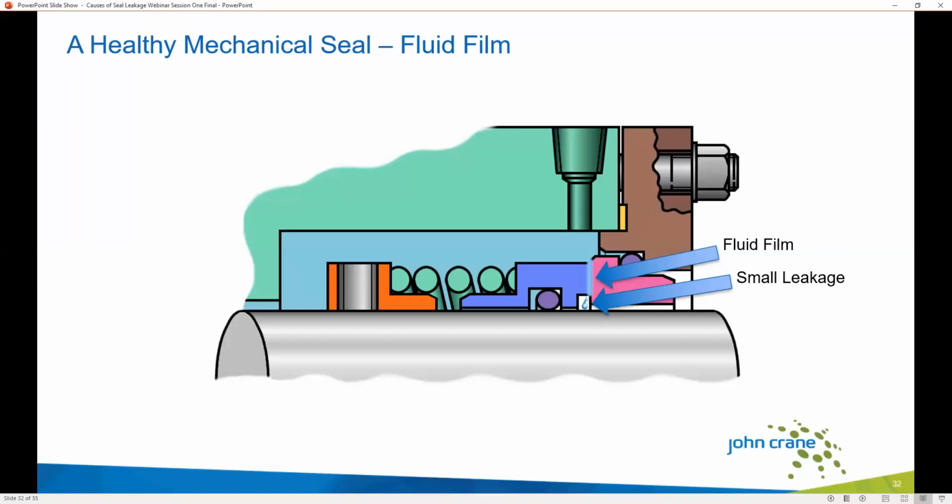It may be that when you construct seals, you often do not see any leakage. It could be so small it's not visible. So for many people, if they can see the leakage, that's their sign that the seal has some kind of issue, hasn't been constructed properly. But even a seal which is working completely correctly will have a very small measurable leakage.